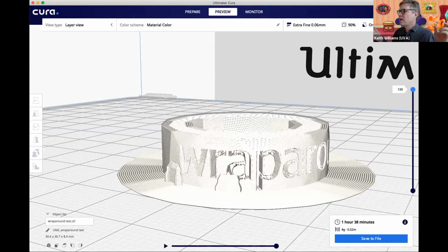So one of the things I always tell people is please don't make, if you're gonna make like the One Ring or something, make it bold. Don't make super small curly cues and stuff that just won't render well in a 3D printing environment in the first place. But yeah, so now your text resolution is limited by the layer height. And so that may not be optimal.